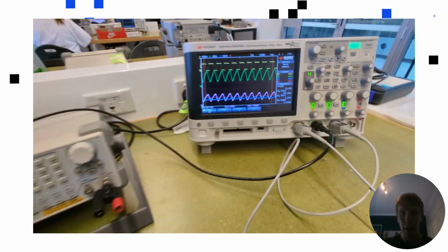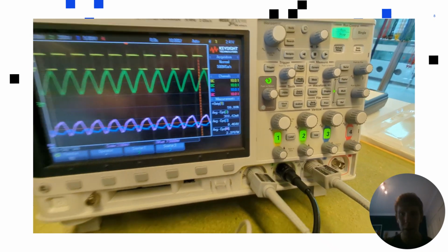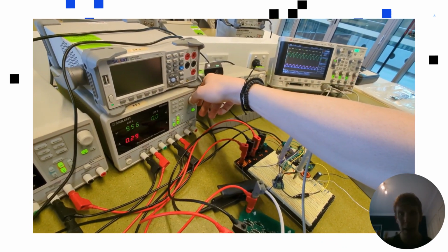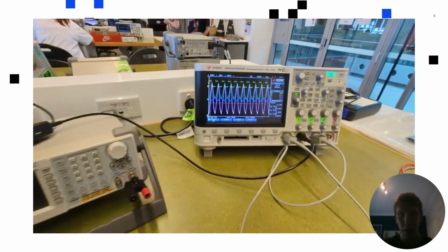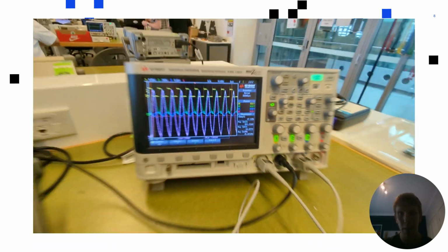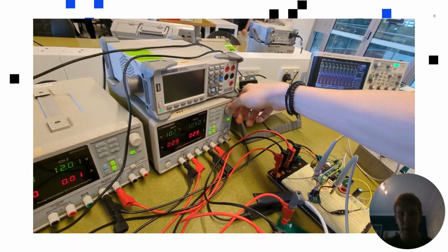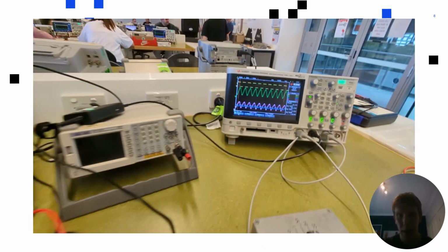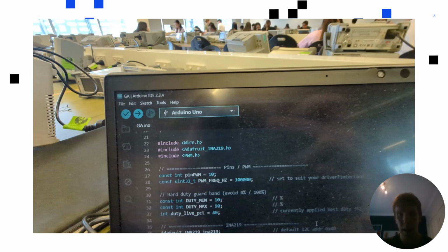algorithm, where in its current operating state we see 2 watts, and if the secondary current limit value is increased to be equalized to the primary, it increases to 5 watts, which is the same behavior observed with the INC algorithm. However, if we decrease this back down to 0.1 watts, we see that instead of going back to 1 watt, it remains at around 2 watts, indicating it's still operating at the global maxima in this condition.